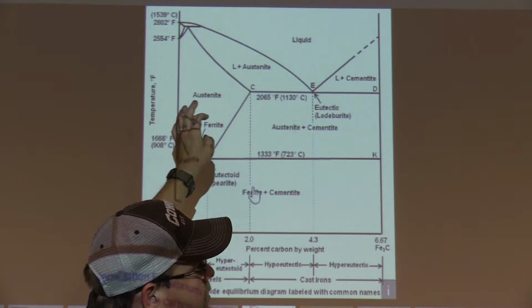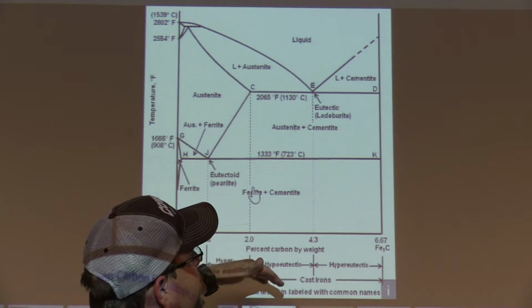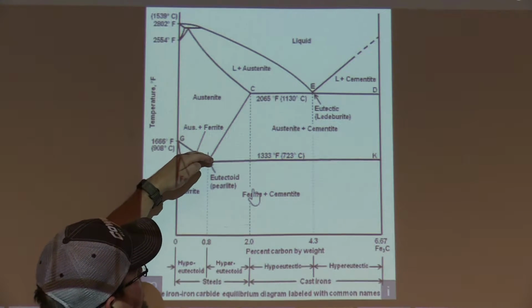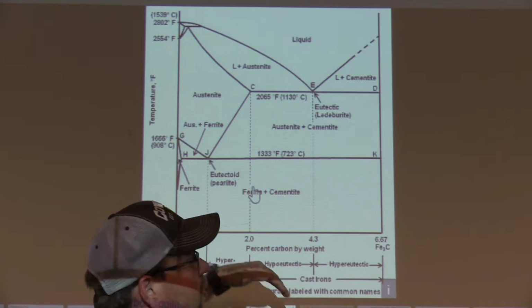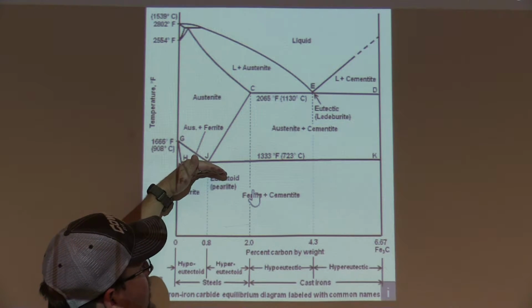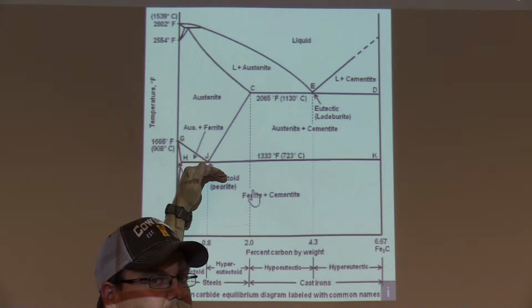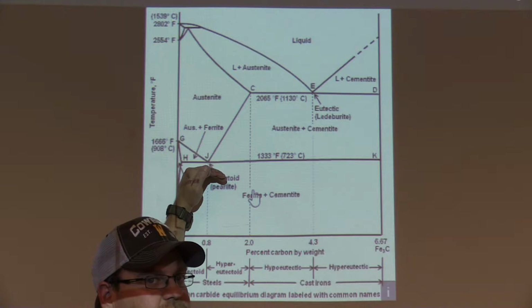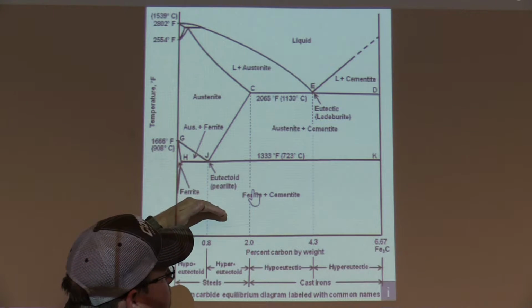That's what happens when we're talking about heat treating, adding strength, quenching things, and so forth: we've taken it to this point. Beyond that, when we talk about heat treatment, what we want to do is bring it back up to right here, below the lower transformation temperature, usually 1,200 degrees. We let it sit there for a certain amount of time, depending on thickness of material, and then slowly bring it back down.